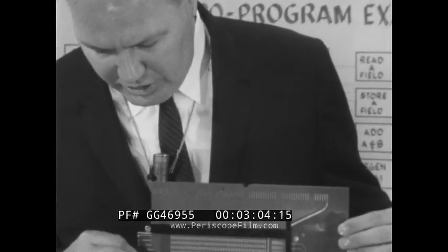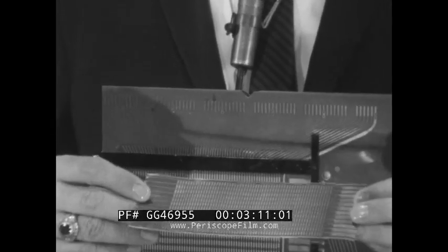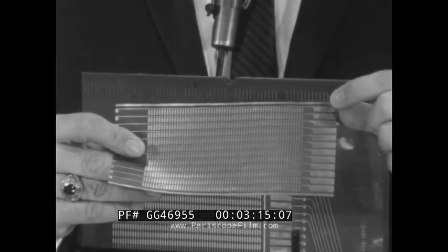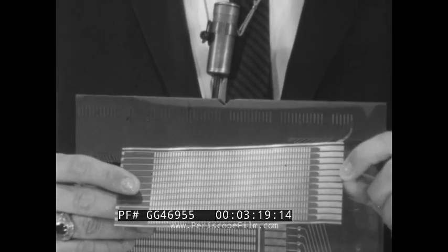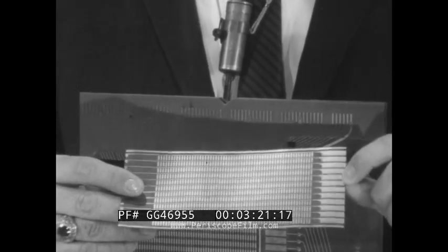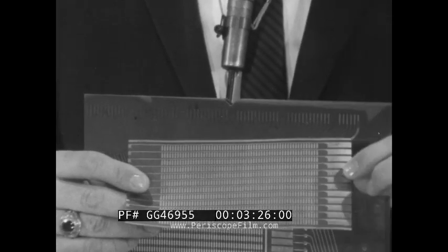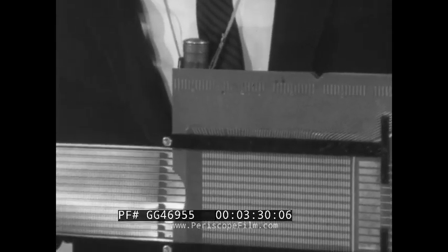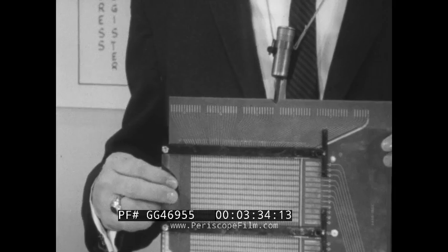Now, by way of illustration of the program cards that are used in this machine system, this is a standard 80-column size card. It has 12 microwords corresponding to the 12 horizontal rows that you normally find on a card of 12 through 0-digit values. It has a series of capacitive plates on here such that this can form, when it's put in the sense plate, what we call the card capacitor read-only storage.